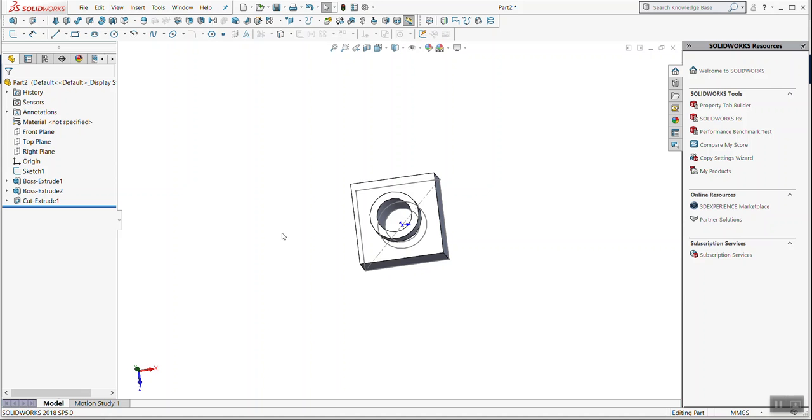Now, typically in the way you order a model, you always want fillets to be towards the bottom. That's just a general best practice rule of thumb for tree organization in SolidWorks. The reasoning for that is fillets tend to be a final step. It's kind of like a final surface detail. So that's one reason to put it at the bottom. The other reason is it's something that tends to change a lot. Again, you can quickly say, hey, I want the object to look sharp, or I want the object to look soft. So playing with the fillets can quickly change that.